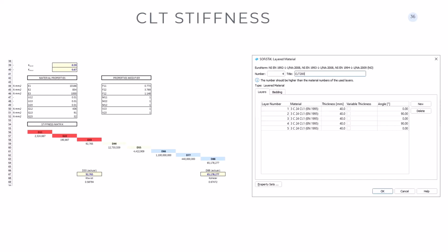It's interesting to notice that if you have different thicknesses of element, you have to define a different material. Before, with a normal material, you defined only the material, no matter the thickness. But with CLT, you have to define exactly this. And by the way, each producer, because of their line, has different lamella thickness and so on. So even the same product, bought from two different producers, will have a slightly different definition and a slightly different stiffness.